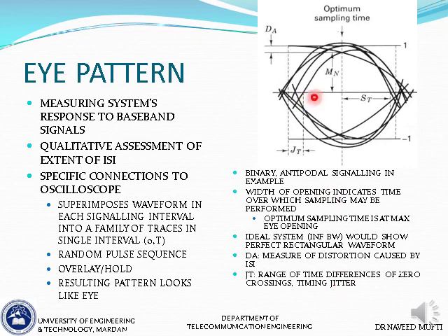The pulses are not rising or falling at the right time. If this is the signaling interval as indicated by these two dotted lines, the pulse is supposed to start here, quickly rise to its maximum value, or whatever the value of the pulse is at that time, and then the pulse is supposed to end here. So again it should cross zero here, but as you can see, there is a lot of fluctuation and a range of time differences of zero crossings. And this is our noise margin.